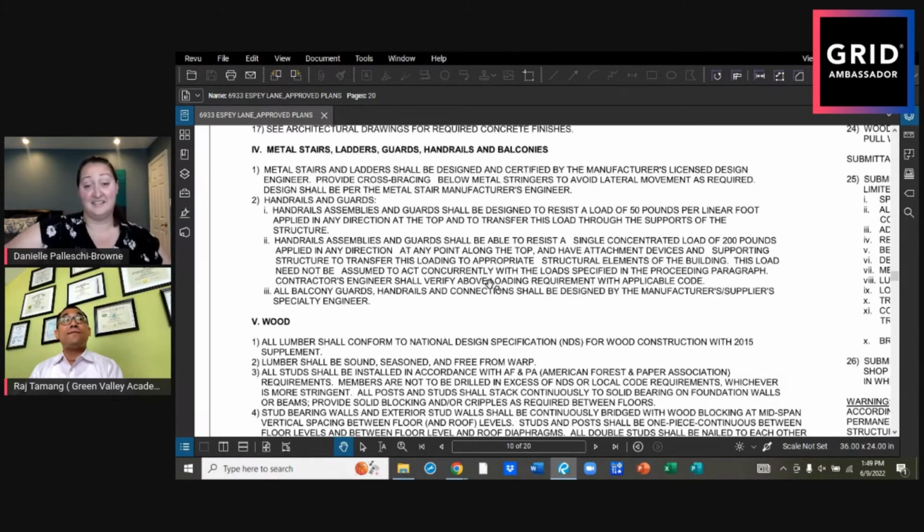And like I said, if there is no water, there is no chemical reaction between the cement and water, and the concrete will not get the same strength. It will just be immature. So you have to keep spraying water. Sometimes they even cover it with a cloth to contain the moisture in the structure until the concrete gets full strength.